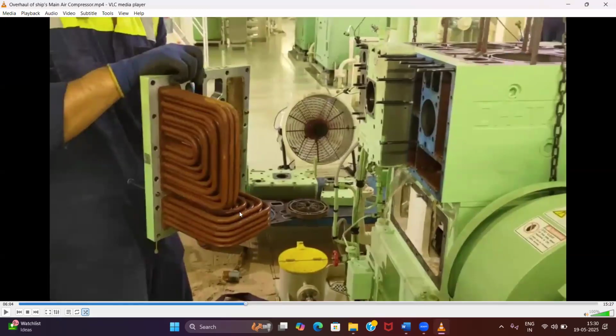See, this is my intercooler and aftercooler tubes. So water is obviously over here. So water is actually a common thing. In the diagram, I have to explain it like this. But you can see over here, I have one set of tubes over here, one set of tubes over here. Do you agree? Yes, sir. And this complete chamber is filled by water. So the water jacket is a common chamber, correct? Yes, sir.